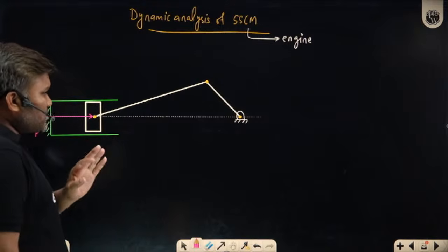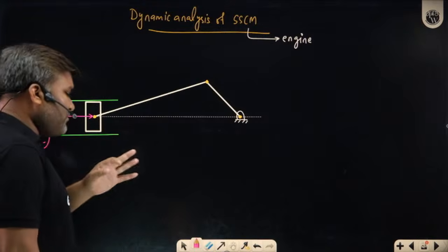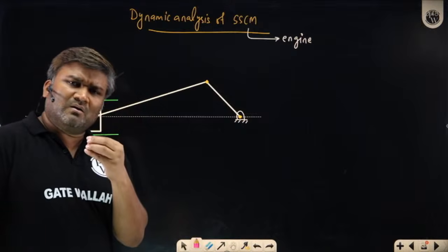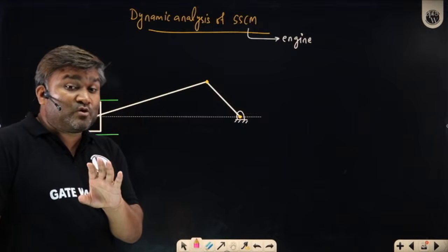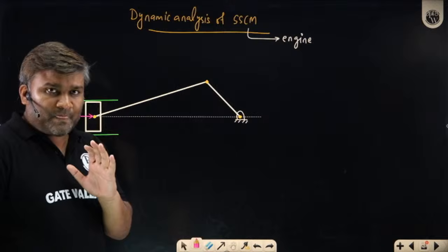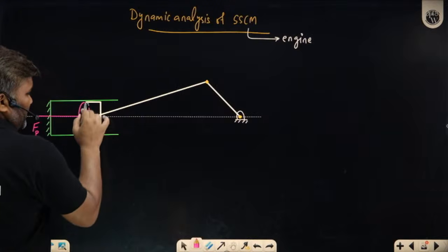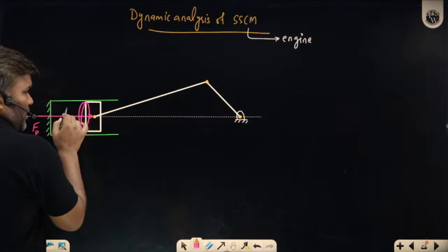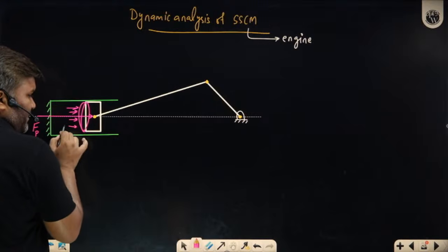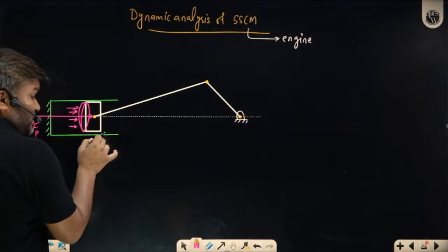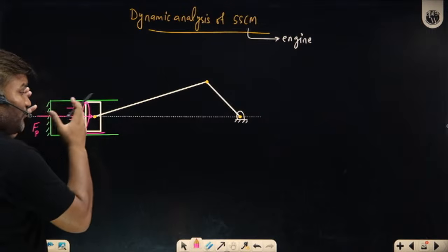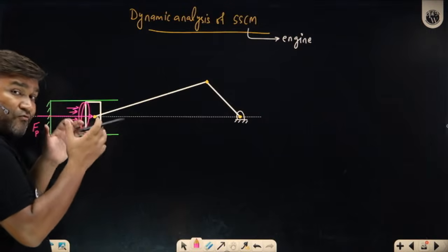So in an objective question, the piston effort value is already given. In a subjective question, they will make you calculate this piston effort: the cross section area will be given, the gas pressure will be given, friction will be given, and you have to find the net force acting on the piston.